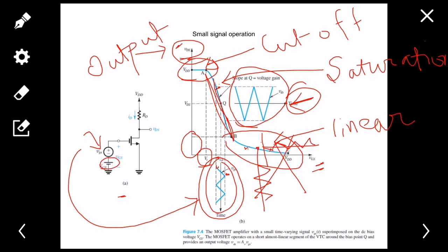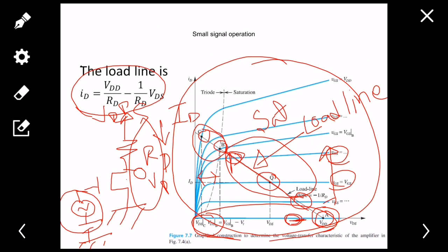Why not just give a small AC signal at the gate? Let's consider this for a moment. If I don't apply this DC bias, what would happen? It's very simple to understand from the previous curve. So this is my characteristic curve. If I don't apply any gate-to-source DC voltage, or bias voltage, then it will initially be turned off.